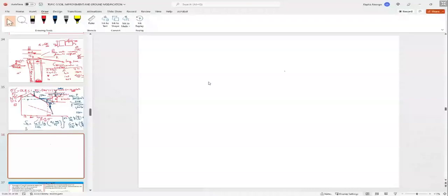Now you pick data for various loadings, and for each loading you pick data for 4 hours settlement and 24 hours change in thickness, so that you can plot. Let me see if I can pull that up. Just give me a second.